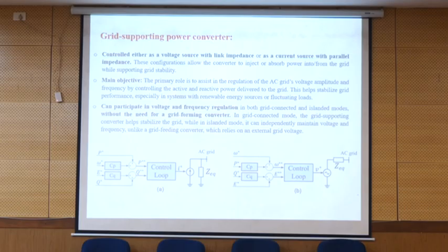I'm saying that if we are in isolated mode, we go to voltage control mode because we have no voltage reference. But when we are in grid connected mode, because we need to be synchronized, we get the information from the grid and it goes to current control mode. And later you will see why we should do it. Do you have any other question?